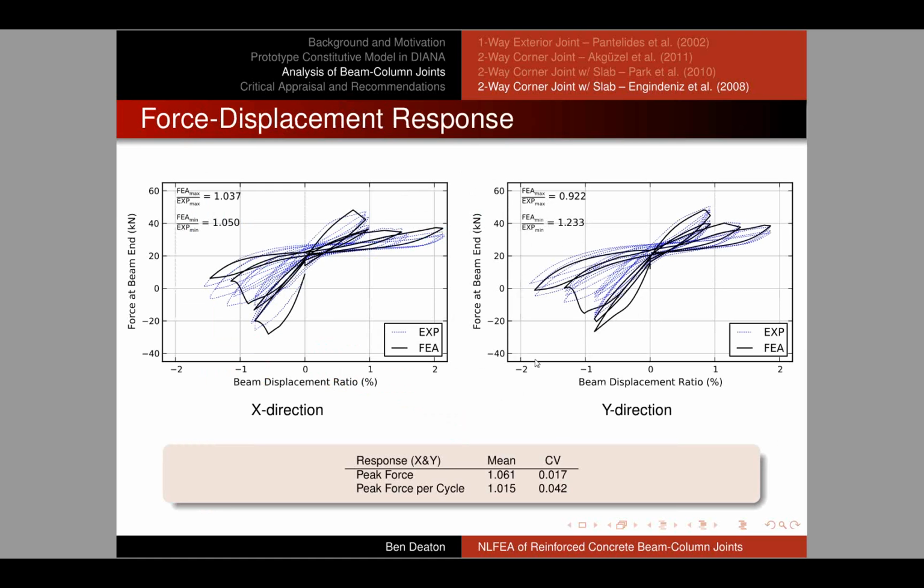Well, this is seen in the force displacement response. So if we look, when we're pushing down on the beam, you can see we have a higher capacity, almost 30 kilonewtons versus, well, actually our datum is about plus 20. So you can see if we're thinking of this as the datum, that we have a difference of about 48, 50 kilonewtons in this direction versus about 30 in this direction. See the same thing over here, much higher moment capacity in this direction versus this.